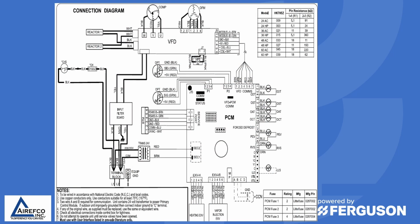This is a diagram of one of our inverter-driven products. You have your VFD and your control board, and on the VFD you have a high pressure switch that is monitoring the pressure of the refrigerant in the system. Again, the high pressure switch may show that it's closed, but you need to check the wiring back to the plug where it plugs into the VFD and make sure that you have a closed circuit there.